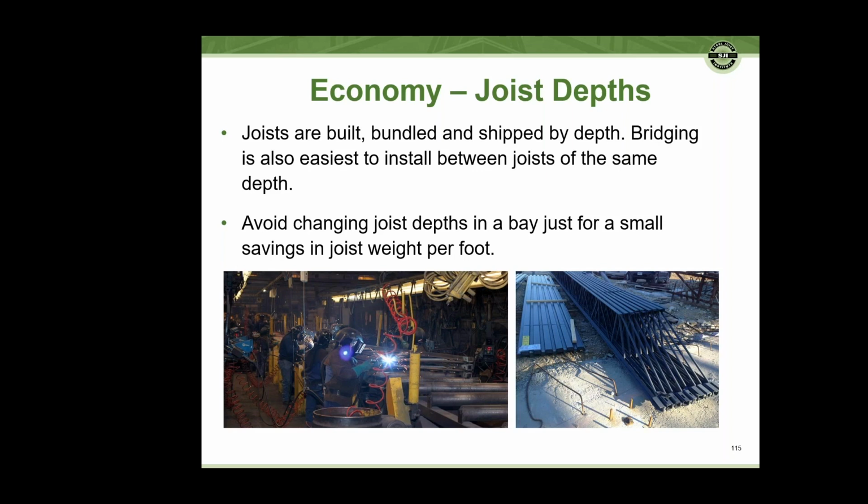So even though, for a certain situation, maybe the joist that has a rooftop unit and has a larger applied load, or let's say we get into a skewed corner of the building where the spans vary, to gain a couple PLF in potential self-weight of the joist would be offset by making too many changes in terms of changing the depth. So again, in a skewed corner, it would not make sense to step down from a 24K to a 20K to an 18K to a 12K. Maybe make one jump in the middle and then go to a joist substitute for the very shortest ones in the corner.